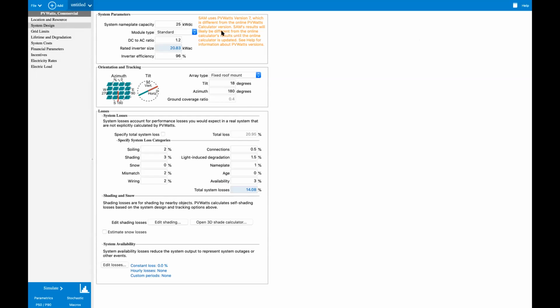And then, the building orientations aren't always going to be perfect if you're doing a rooftop. So this one was, let's say, at 135 degrees. So we're not necessarily facing true south. And this is one of the things you can use the model to compare: is there a benefit from putting it on the ground versus on the roof if it's not ideal situations?